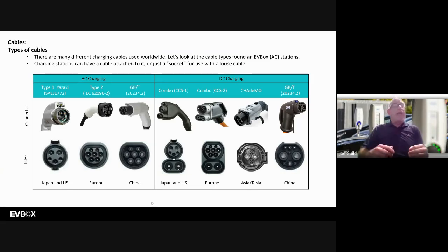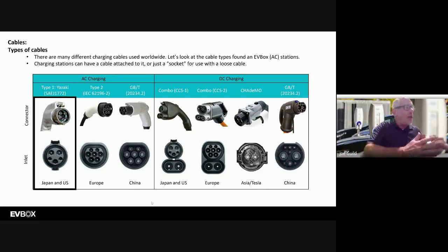As far as charging cables go, we're really trying to consolidate this now. In the beginning, this was really 2 years ago, we had 2 different major cables for AC. A Type 1 for the U.S. and the Japanese cars. Remember, the U.S. and Japanese grid networks, at least at the time of manufacturing of the cars, were only one phase.